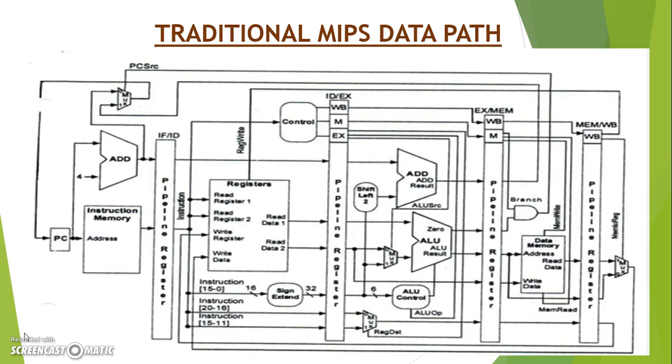Every instruction in RISC architecture can be implemented using 5 clock cycles. The 5 stages are the union of all the operations required by all the instructions. That is, they are the instruction fetch, instruction decode, execute, memory access, and write back.